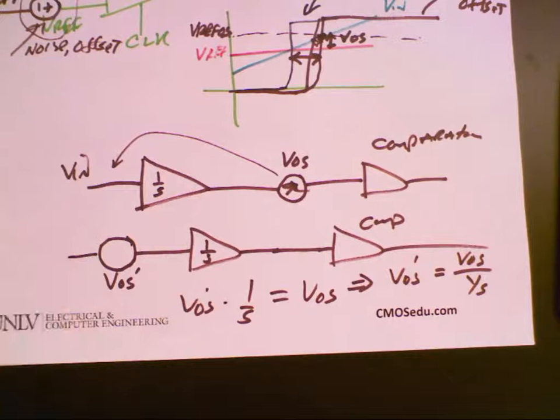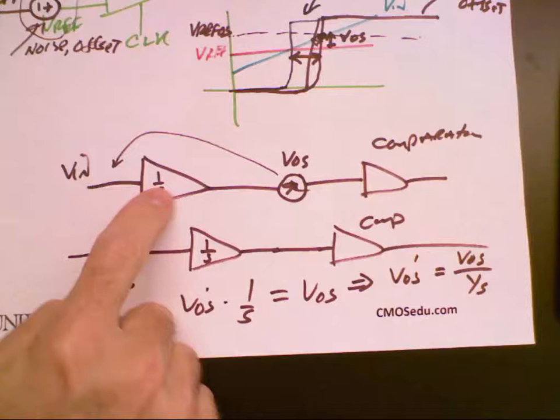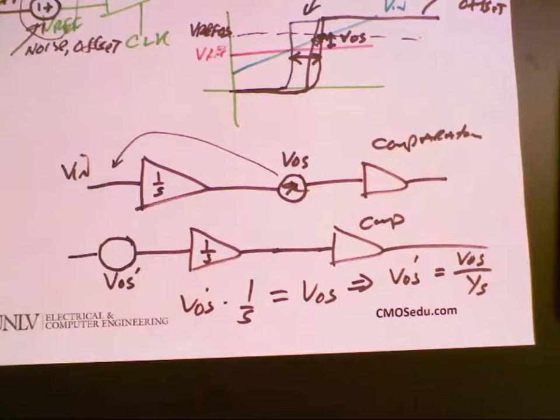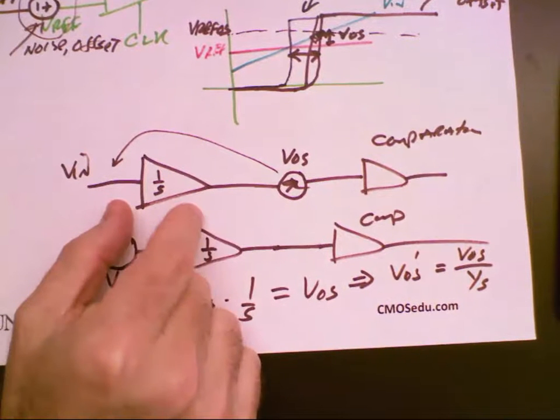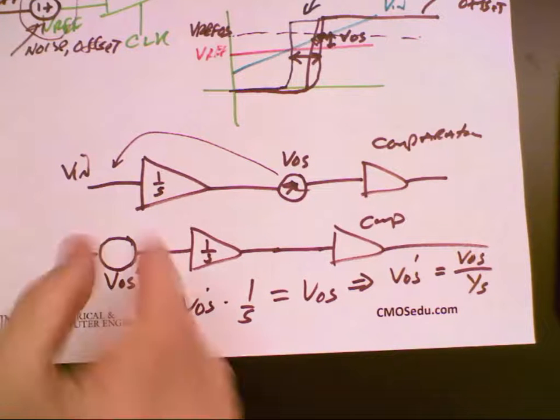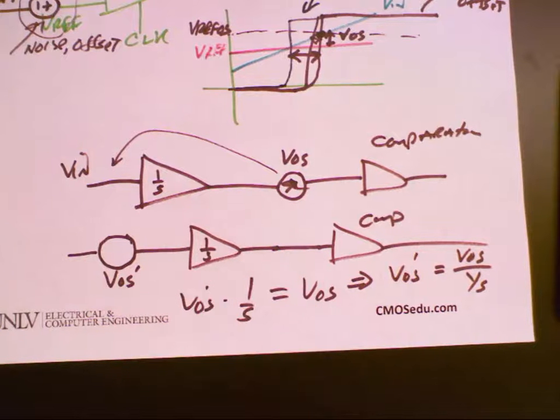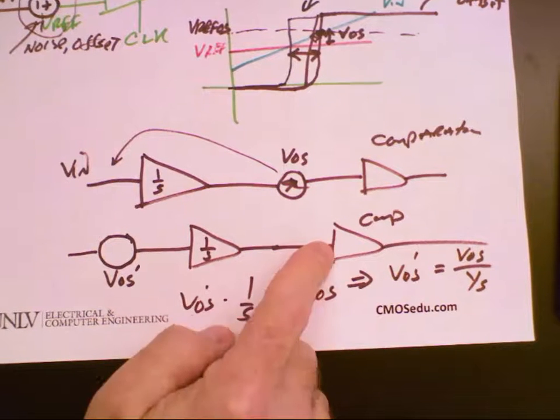The key point is, because I've got this really high gain stage, and keep in mind, it will be high gain because when I'm doing oversampling, that's one of my requirements, is that this is high gain in the signal bandwidths of interest. This noise from the comparator will be pretty much irrelevant. If I make a mistake, it's pretty much irrelevant.